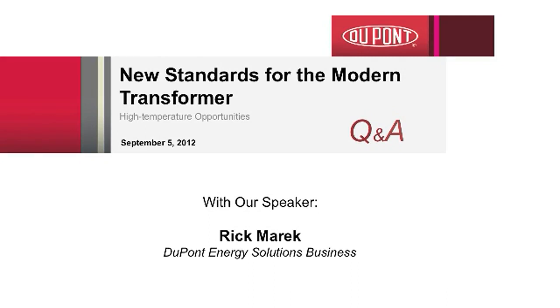Trackside rectifier transformers, for example, would be a good application, largely because they see very severe loads and then long periods of idle load conditions. So the large changes make a high temperature transformer a good application.